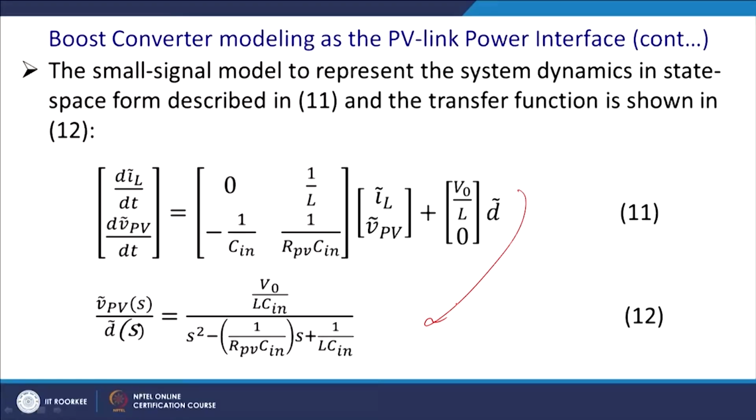It has an A matrix and a B matrix, and you know how to convert state space to transfer function. This is the state space, x dot equals Ax plus Bu, where this is the A matrix, and u here is the change in the duty cycle.